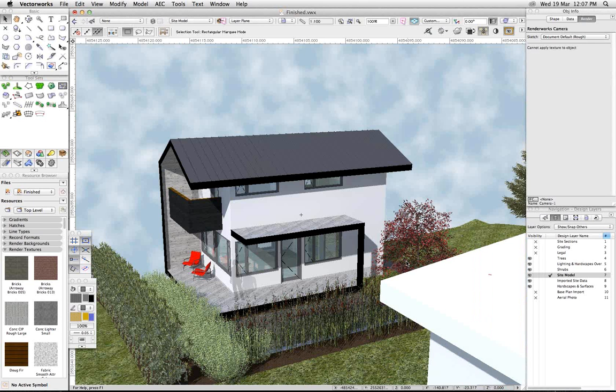So with that said, I will wrap it up because I'm a little bit over time, but there you have, coming from scratch, a site model whereby we put together 3 separate pieces, all in registration of geo-referenced coordinate system, and then modified the site to kind of push and pull to a proposed site model from the existing by use of these various site modifiers. Okay, Kevin, I'll turn it over to you and see if we still got time for a few